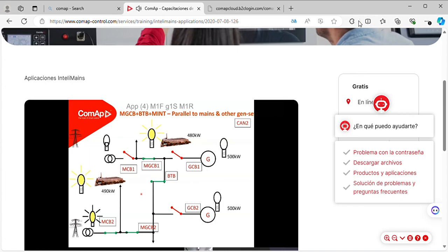This is pretty common these days in data centers or hospitals, which usually take a dual substation feed into their system, and they can switch to substation 1 or substation 2 if under any scenario one of the substations fails to supply the power. It's pretty straightforward, and we can couple the buses by using a bus tiebreaker and start feeding from substation 2 to both the buses, say the IT load and a building load or compressor loads. Or if it is a hospital, the critical and non-critical systems can be combined.